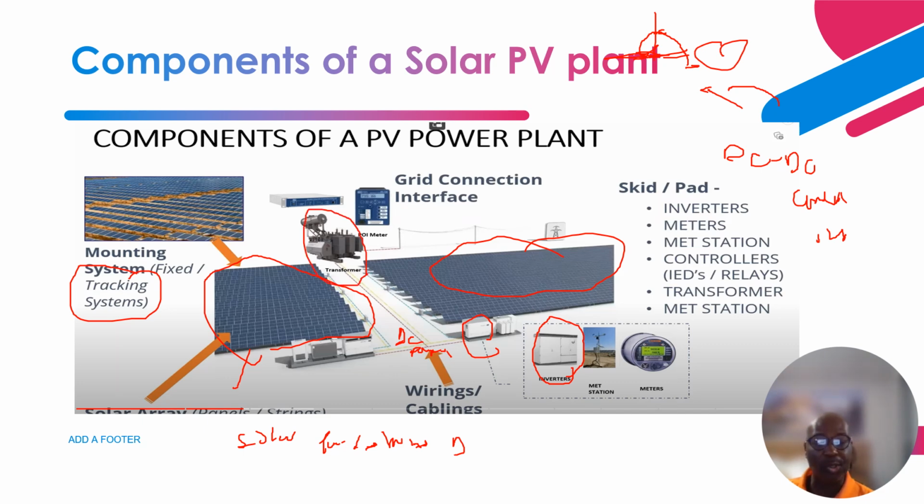It goes through the step-up transformer, and right at the interface before it gets connected to the grid, you have mirroring. You need to mirror what you're selling to the grid. Then there are other controllers that allow the interconnecting utility to send set points, and also curtailment, if they need to curtail the production of solar power, so that you can go into island mode. So there is a controller here that interfaces with all the plant equipment and also the grid.